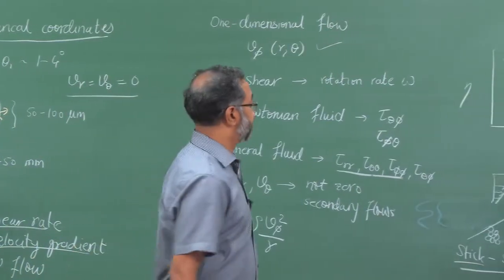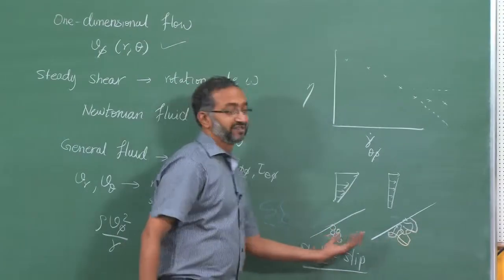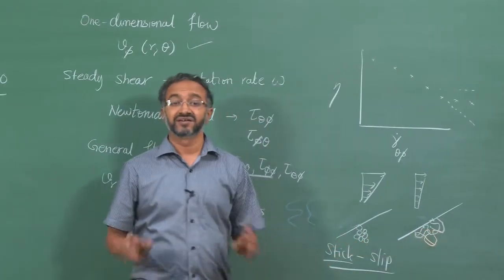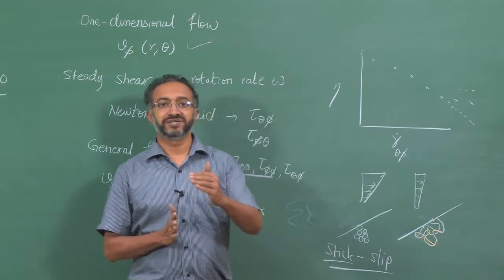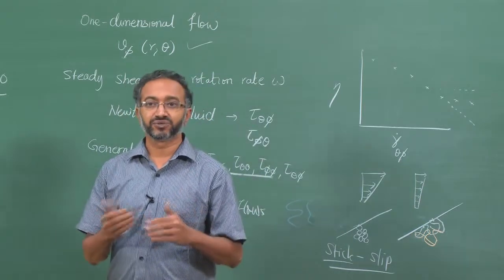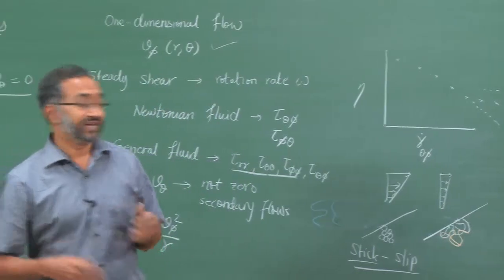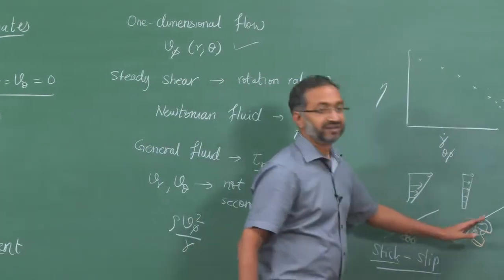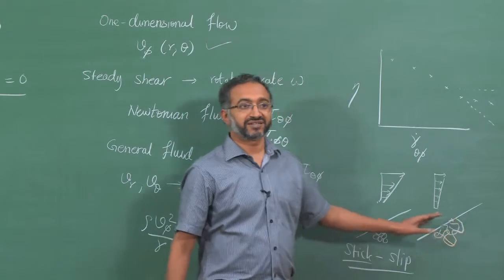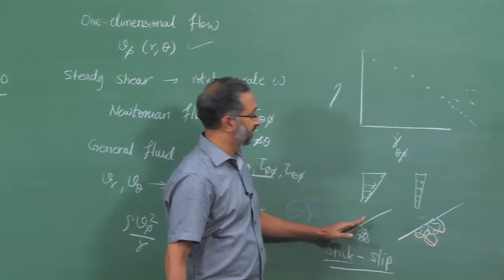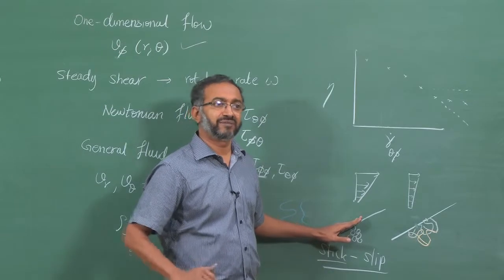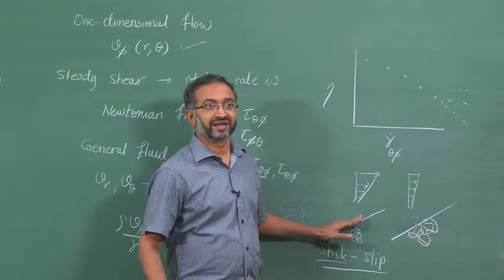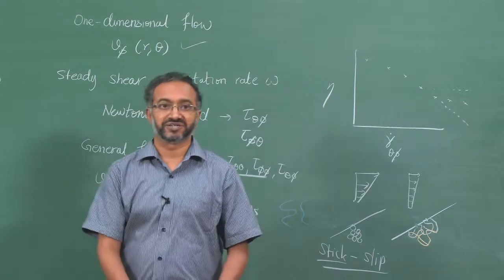That generally depends on the extent of interaction within the material itself and the extent of interaction between the material and the surface which is being used. So, one easy way to modify slip would be to change the nature of this surface. For example, if you suspect that adhesion between the particle and the surface is not good, you can modify the surface to make the adhesion even poorer and then see if I get even less viscosity.